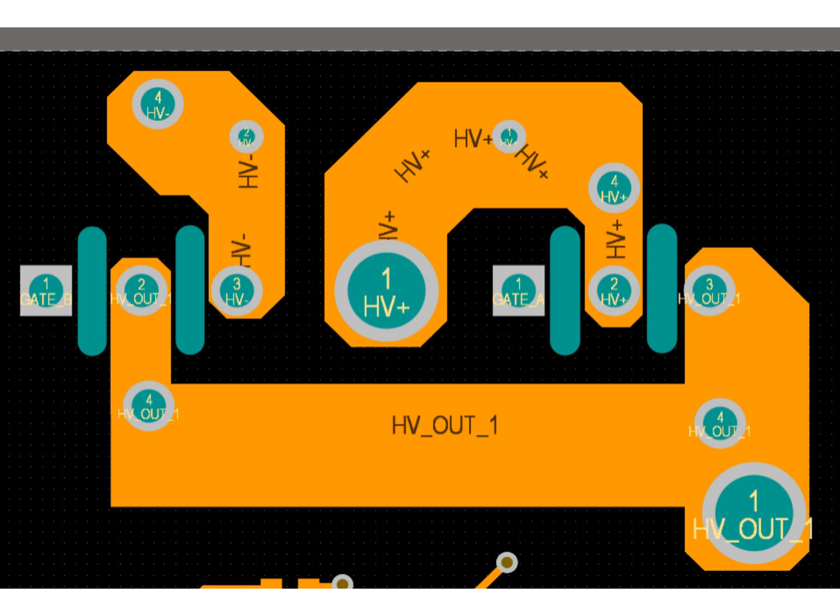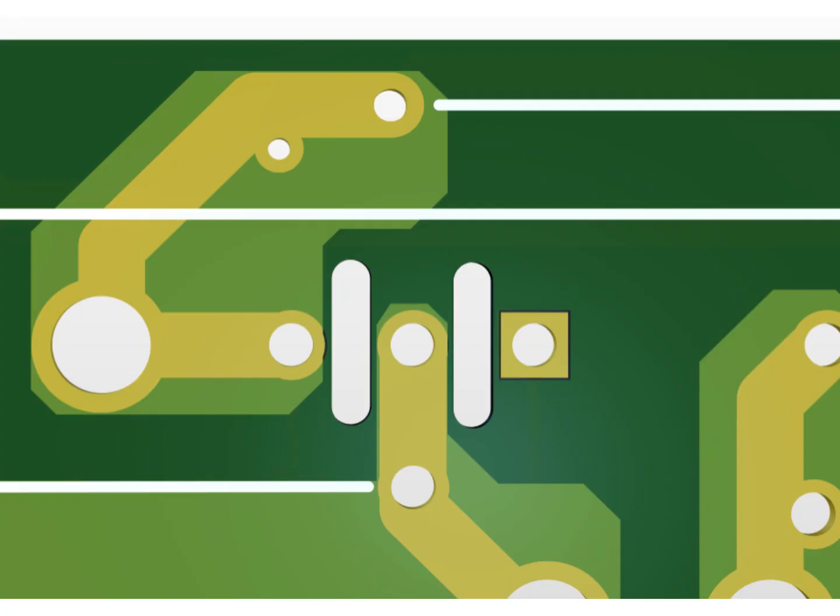In addition to the larger via size, the current carrying capacity of the PCB tracks is further increased by soldering copper conductors directly onto the power tracks and vias. This effectively increases the cross-sectional area of the conductor, reducing both resistance and temperature rise. By combining large diameter power vias with reinforced copper tracks, the board can handle high currents without overstressing the copper or the vias.